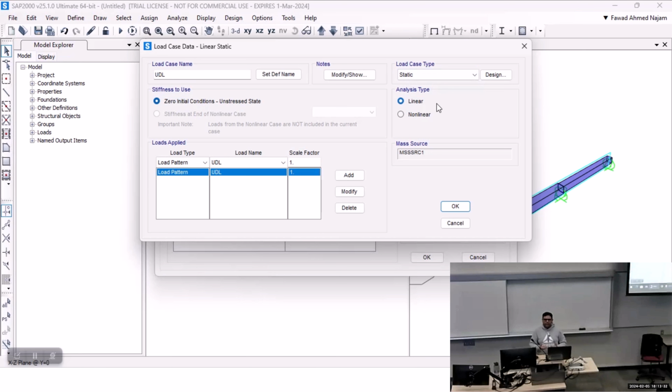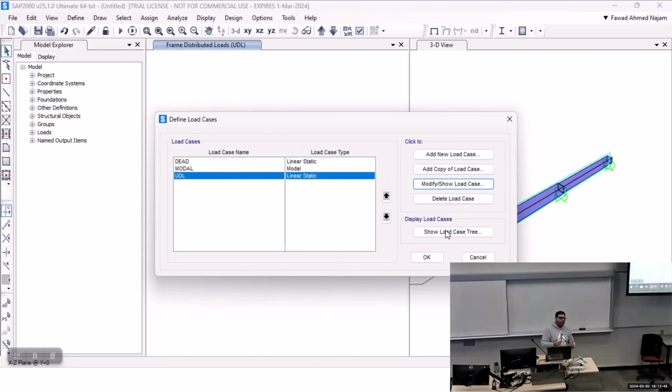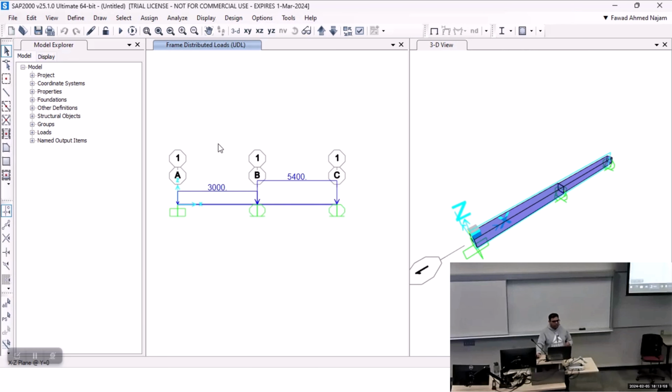It is linear analysis because your computer model is linear, it has a constant elastic modulus, and it does not have a feature to go into the non-linear range. So, the elastic modulus will remain constant for this model. The program can automatically create a load case once you define a pattern and add loading in that pattern, so you can simply review this option before running the analysis.